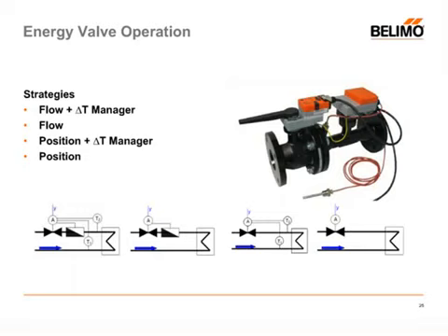The valve can also be operated in flow mode, or basically pressure independent mode. The valve can also be operated in position mode, which would be basically pressure dependent, and pressure dependent with a delta T manager, or pressure dependent without the delta T manager. So 4 modes of operation, but basically a variant of 2.